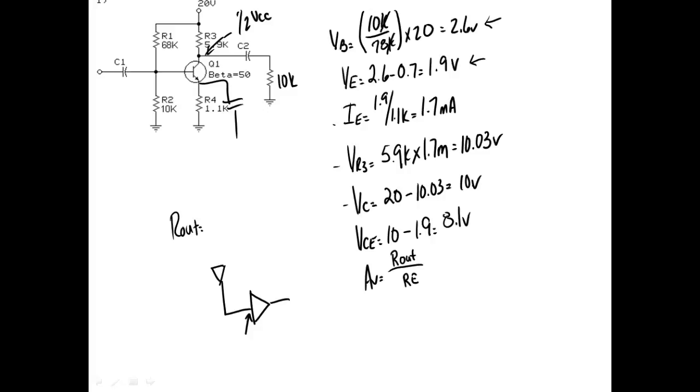If I come over here and this is my antenna on my car radio out there, the first amplifier I go into, do we want it to have low impedance or high impedance? How much of a load can an antenna drive? Can an antenna drive a speaker? No. Low impedance means it's got to provide a lot of current. High impedance means it doesn't have to provide a lot of current.